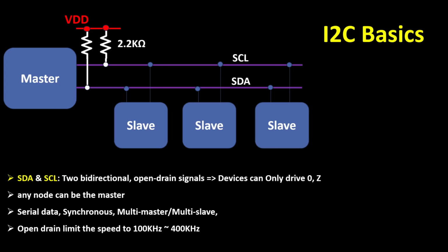I2C is a serial communication protocol based on two wires, serial clock and serial data. It's asynchronous. Why is it asynchronous? Because the master node is sharing the clock between all the slaves that we have in the I2C network. Both clock and data lines must be pulled up to the power supply, and both master and slave need to work with open drain. What does it mean to work with open drain? It means that their output only swaps between 0 and high impedance Z.